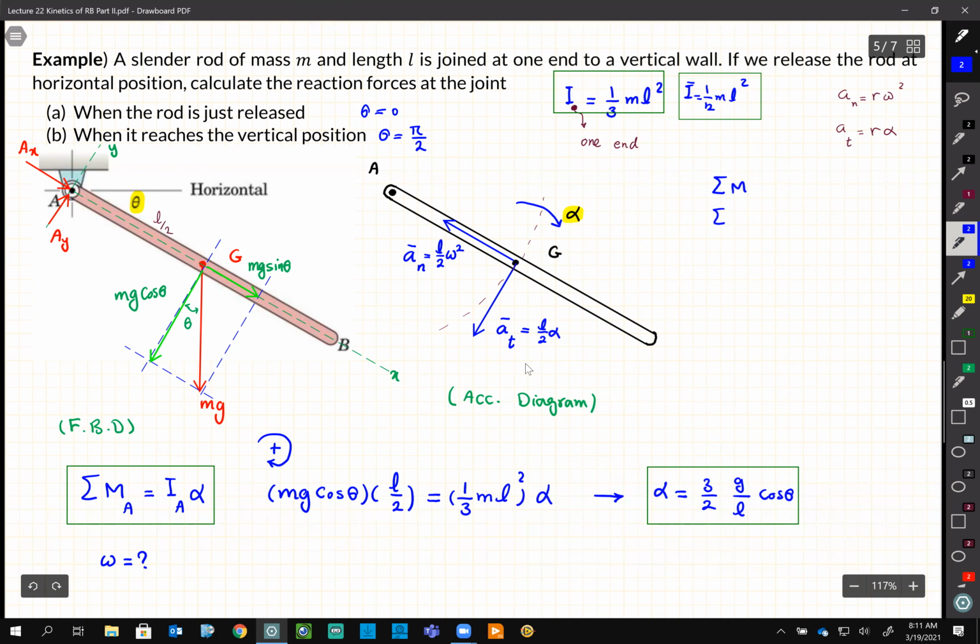And then some of the force equation, m a bar, and this one I bar alpha. Or other equation, like here in this scenario, we will use I_A alpha, and we write the equation about point A. So if I look at my a bar, I can notice that I have omega here. So I need to figure out the speed of this link. So I have some formula for omega. Do you guys remember how we can calculate omega?